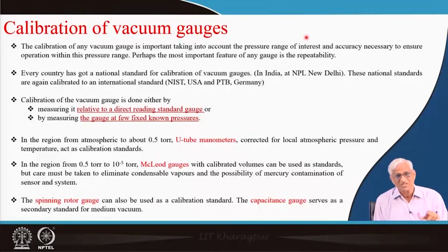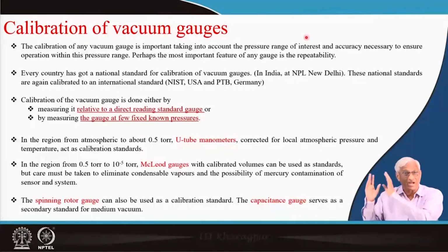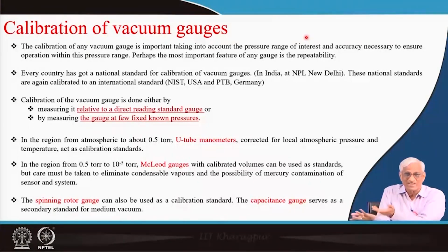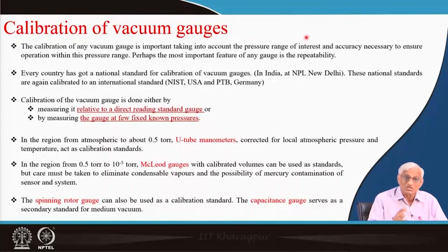Semiconductor manufacturing requires it, because you will not make semiconducting oxides. Once it is done inside, monolayer formation should not be there, you should make P and N types and all those things, and if you do not do ultra high vacuum, you will not get chip manufacturing. So, both of them require very good measurement of high vacuum. 10⁻³ torr, which has removed 99.99 percent, is not good enough for semiconductor, nuclear and space technology and metallurgy.